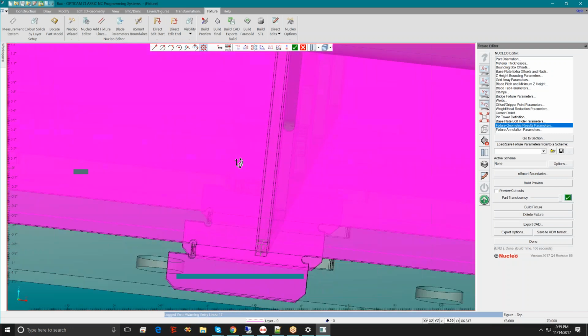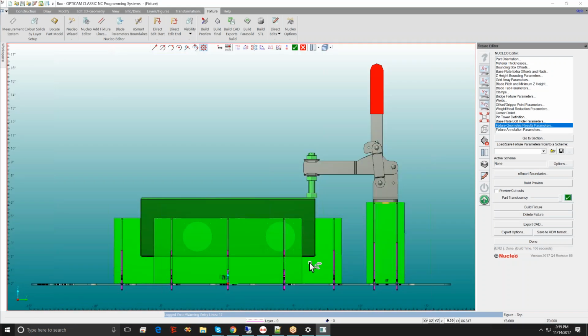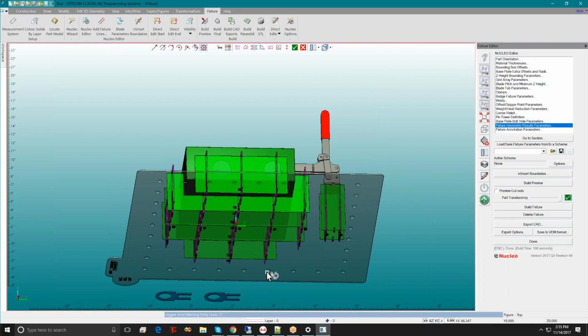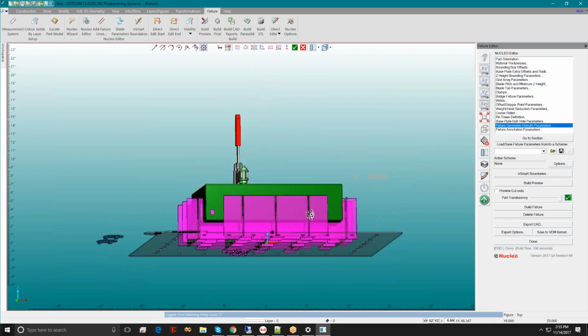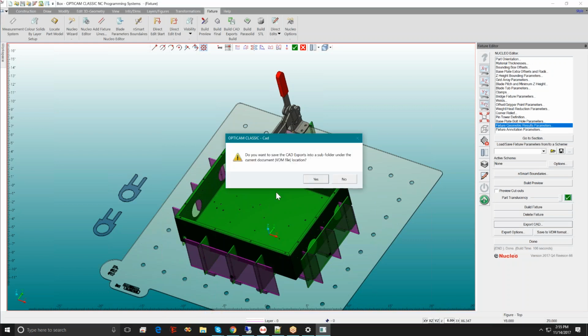So if you didn't want that, you just wanted it to be flat, you would remove this parameter and just make the depth of the thing only 1196. Or say if you had a 1/4 inch base plate, you would put 0.25 in. Because in this case, we're going to have to put this up on some bushings. You'd have to put some bushings on the table just to offset it from the surface of the table. So once you've got this done, you're done. You could export the CAD files. I'll do it for the sake of argument.